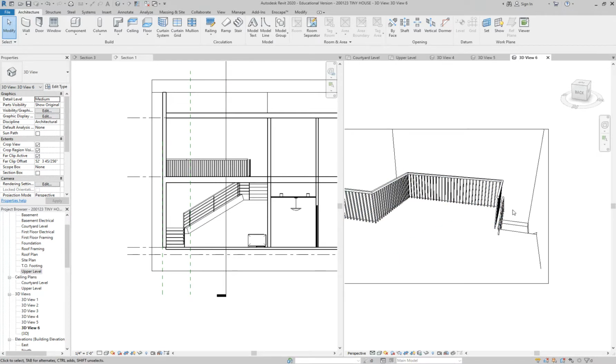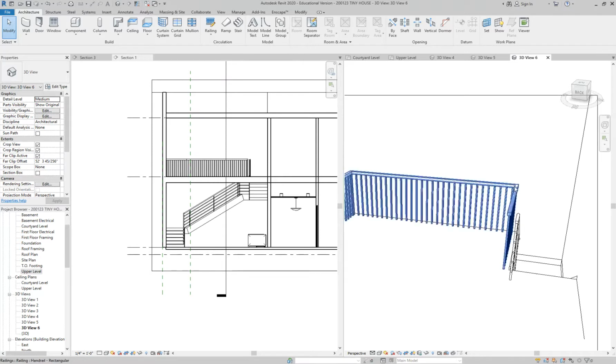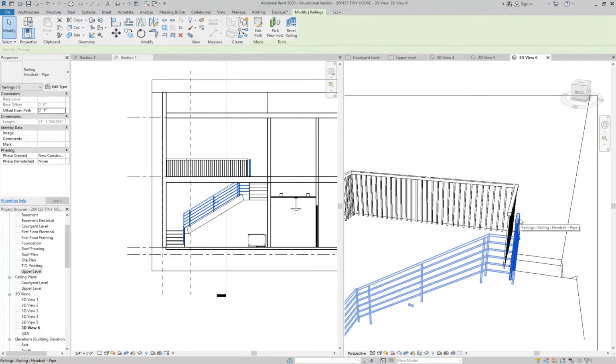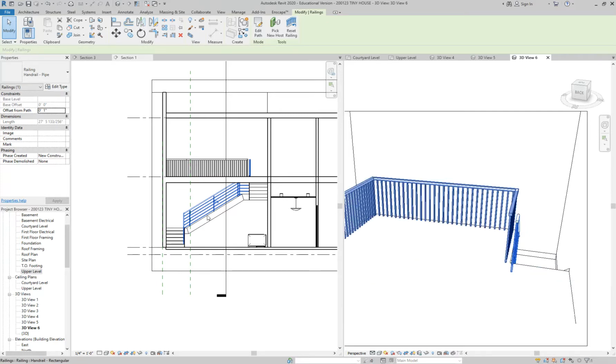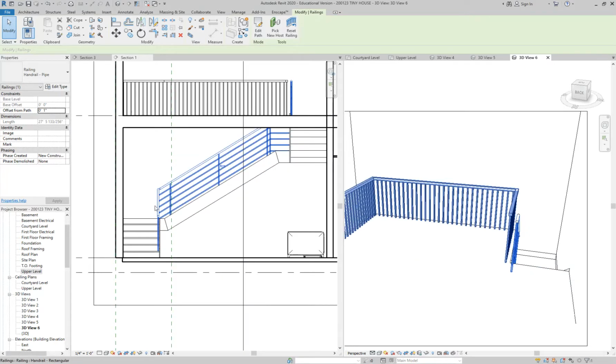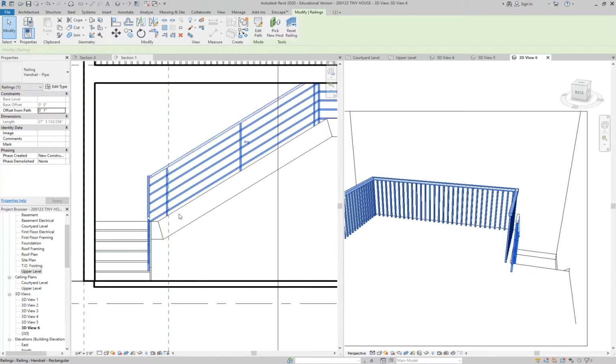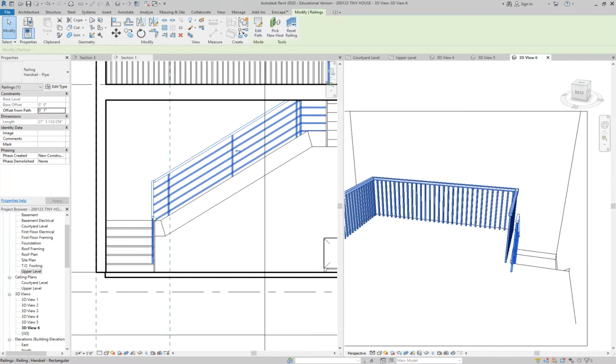Just a couple other things that you can do in here. So you can add a railing separately. You can edit the handrails separately. They are independent from each other. They draw them in automatically, but you can edit them. And you could even come here and edit the length of this one. I don't know why you would do this, but let's say you'd want your bottom 4 stairs to be open.